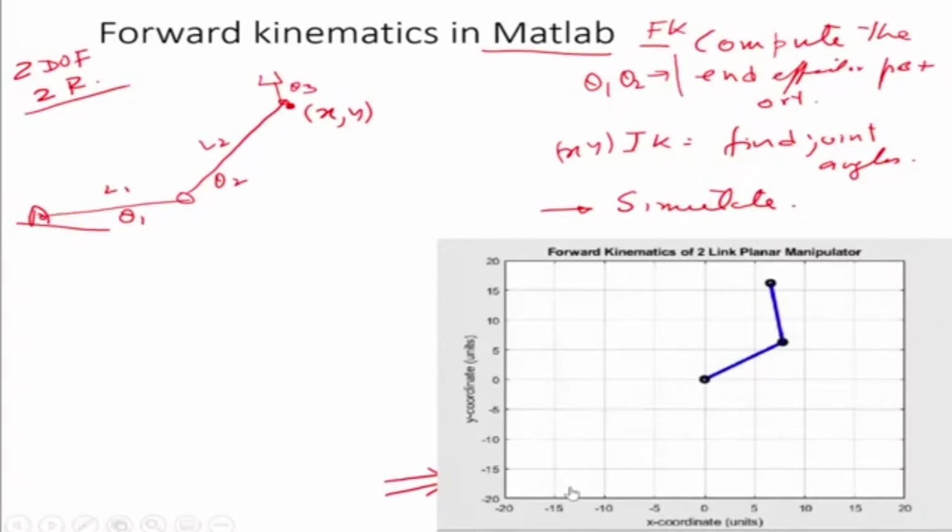So the first thing that we do is to make our DH table. Well, before that we have to put our axes. So this is my Z0 and Z1. This is my Z2. That's my Z3. This side is X0. This is X1. This is my X2, and that's my X3. The link lengths are L1 and L2.